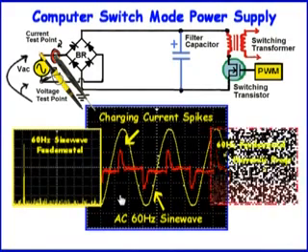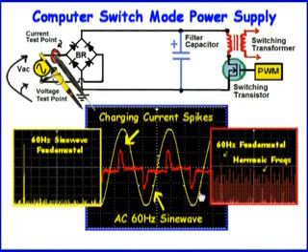Whenever an AC sine wave is distorted, AC current is redirected from the 60 Hz fundamental into these harmonic frequencies that produce no useful watts. They only heat up components and cause electromagnetic interference.